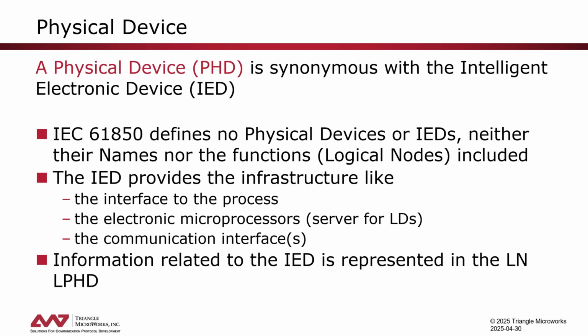The IED itself has the infrastructure, of course, like the microprocessor, the power supply, but it also has the communication interfaces and the interface to the process where we can connect our system to the switchgear, to the breakers, but also to the current and voltage transformers.